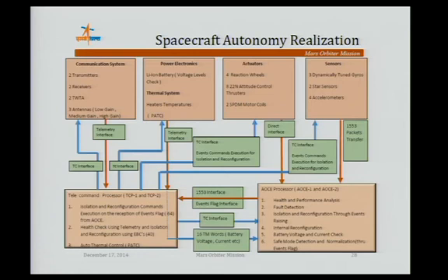And the basic processor system, the telecommand system, is on the left side of the slide. Similarly, the AOC system is on the right side, where it does health performance analysis, fault detection, isolation and reconfiguration through events, and internal reconfiguration. It also does battery voltage and current monitoring checks, and safe mode detection and normalization through events. All the detection takes place here, and real command execution takes place through TCP, which generates the command for other subsystems. All are communicating through the MIL1553 interface, and telemetry parameters coming from the battery and other things go from TCP to AOC.